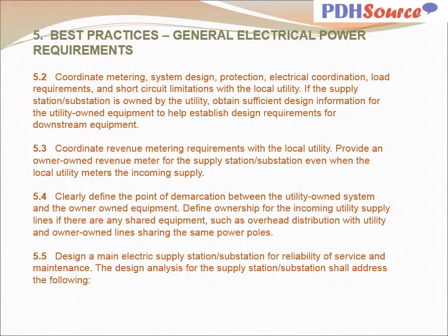Clearly define the point of demarcation between the utility-owned system and the owner-owned system. Define ownership for the incoming utility supply lines if there is any shared equipment, such as overhead distribution with utility and owner-owned lines sharing the same power poles.